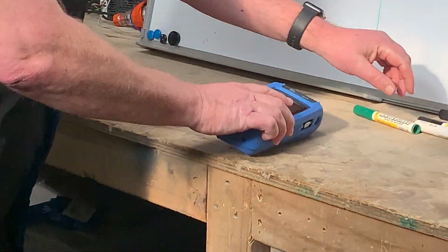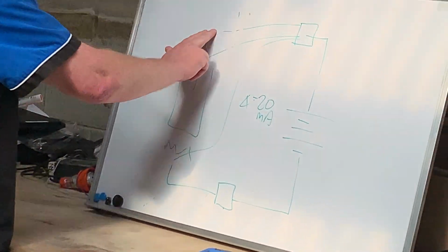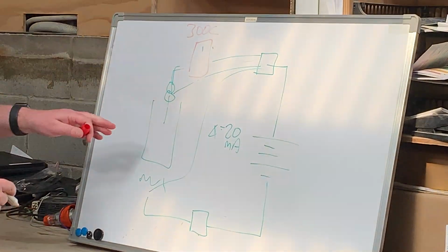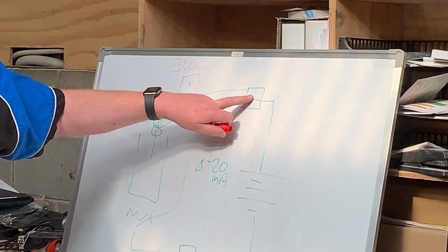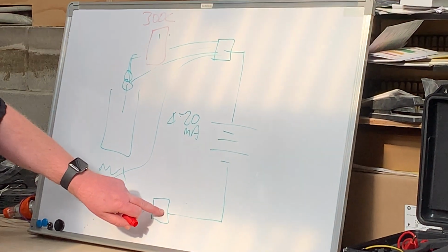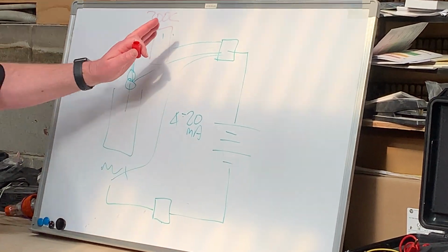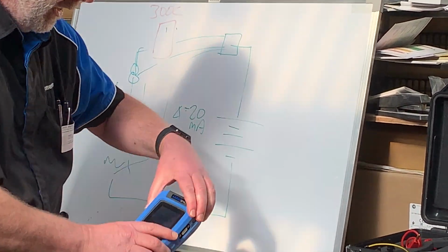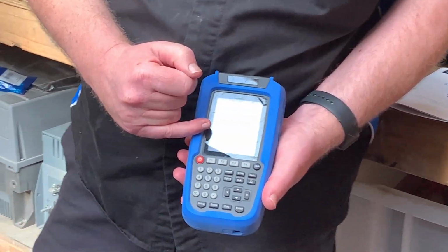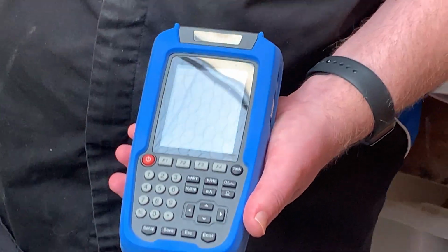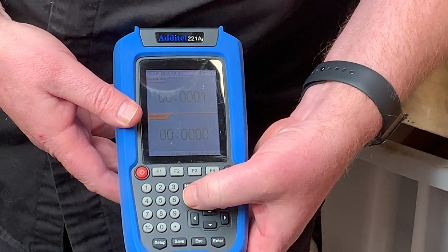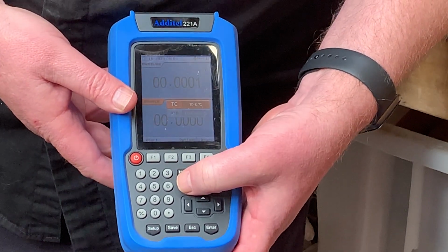So what we're wanting to do is pretend that we're a thermocouple at 300 degrees C, and we want to see that this is 300 degrees C. We want to see that perhaps this gas controller responds at different temperatures. So we might ramp it up and down. I'll show you that. So what we want to do is source a K-type thermocouple. You see why? Yeah. Makes sense? Yeah. So if I hit the thermocouple RTD button, source measure, so we go to source.